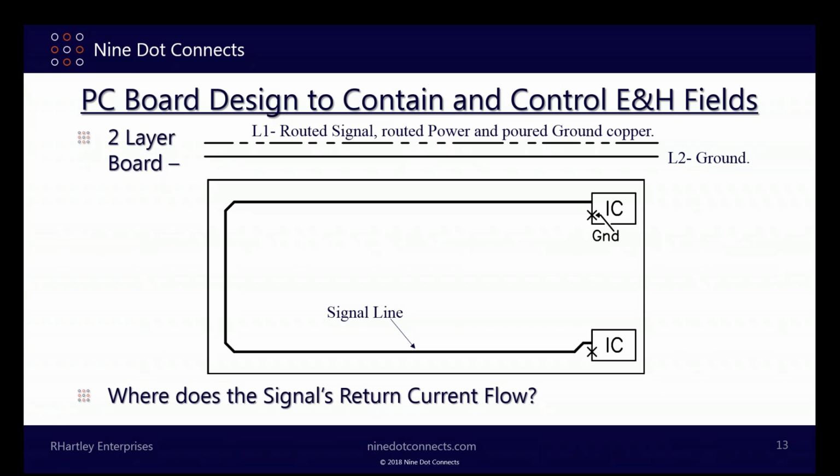As you go up in frequency, by the time you get to a few hundred hertz, the energy would start to focus itself in one place on the plane, one place and one place only. And by the time you are above a kilohertz, and certainly by the time you're out of the audio range, 100% of the return current will be directly under the trace back to the driver.